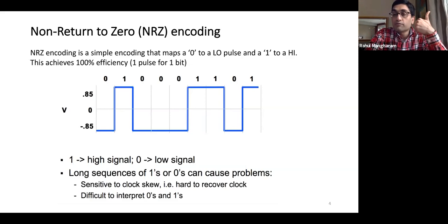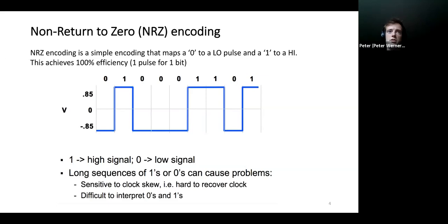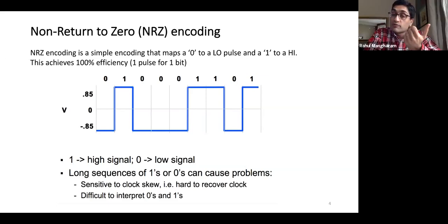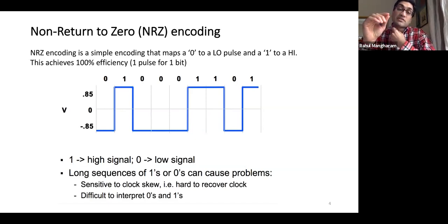What are other kinds of problems that we could have with our crystal and our timing? Maybe varying frequencies. Yeah, so we could have different frequencies, right? It just means that I'm running at 16 megahertz minus 20 hertz, and you are running at 16 megahertz plus 20 hertz. And so therefore you're always running faster.